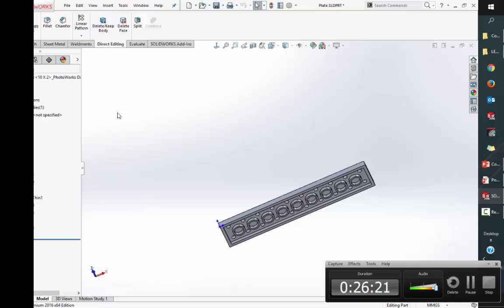I take that whole little row, copy it to the bottom, adjust the numbers real quickly, say okay, got the part done. Already done. In fact, on a good day, I can get in there and probably create it in about 15 seconds. So way easier than going and creating a new configuration, figure out what features I want to control. Now I'm just copying a variable down and I'm just adjusting the whole thing. In fact, with the design table, you can even go a little bit farther and you can make it more intelligent by adding equations into the design table that will start running numbers. You can have validation in there. You can do anything in Excel you can do in there, all right?